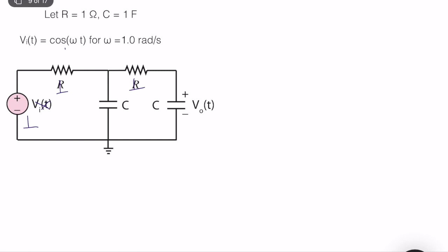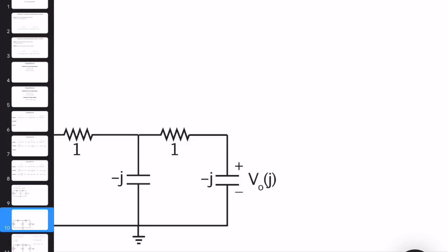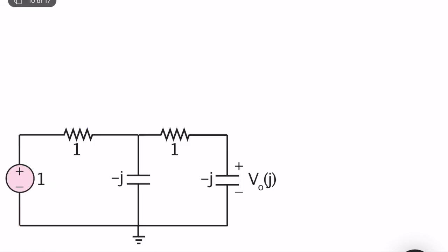So what is the impedance of the capacitance? It is equal to 1 over C times j omega. Omega is equal to 1, C equals 1, so it's 1 over j omega, and we know that 1 over j is equal to minus j. So if we transform everything, we will obtain this. This is minus j, and we will treat it as if it's a resistance in resistive circuits. Nothing will be different. It's complex, it may be non-intuitive for many of you, but computationally it's super convenient.